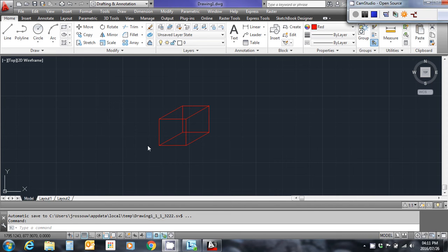Now, there are some very specific things we need to do in order to meet the objectives of the Drawing 2 module as part of your National Diploma Civil Engineering. Remember that we are technicians that draw. We're not pretending to be draftsmen per se, so we're going to follow a methodology that is going to work for us. The first thing we need to realize is that this cube has been drawn in model space, and as part of our curriculum we do not print drawings from model space, although other people do it, and you can do it if you know what you're doing in industry one day. I don't recommend it. I think the best convention for us is to print our drawings from the layout environment, or the paper space environment as it were.